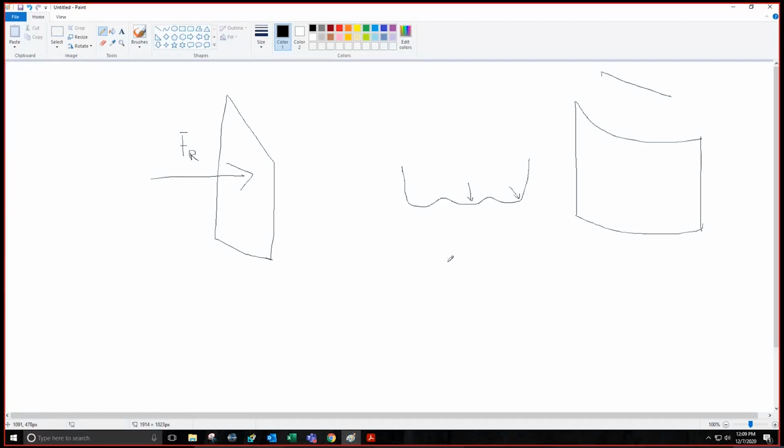We calculate the formula for Fr using a differential point on this curved wall, which we define as dF, force dF, and the area of this differential point as dA, and then we integrate dF. So dF equals pressure into dA, and we calculate this pressure. But this dA integral will not be that simple for a curved surface. That's going to be too complex for the curved surface.